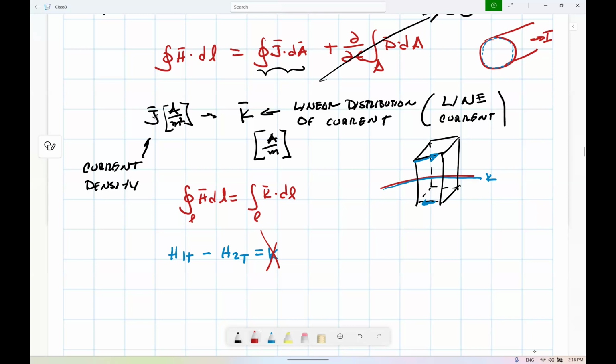So you can validate it slowly, by building more and more on a complicated model, or use some approximate analytical solution to see if things make sense. So in that sense, analytical solutions have some value. If you cannot do an experiment, build first, as we have done with Fayaz, the analytical solution with your finite elements. You say the analytical solution of a cylinder is this one because you know it. So you build that one first, and now you can deform the materials to the right thing, once you have already validated that your solution makes sense.